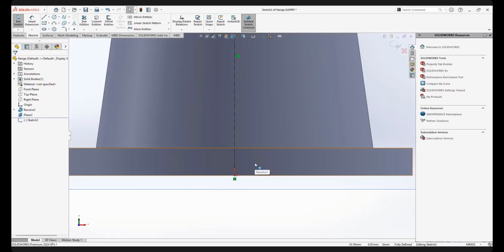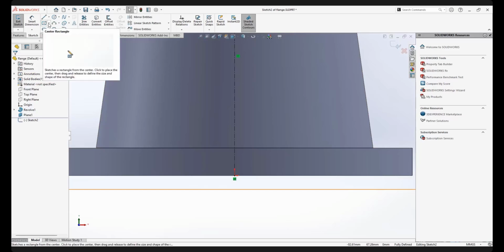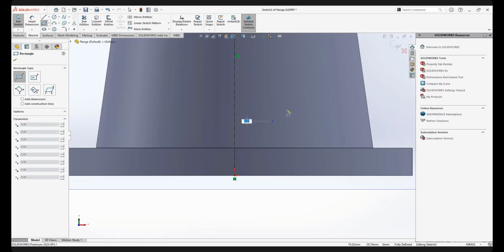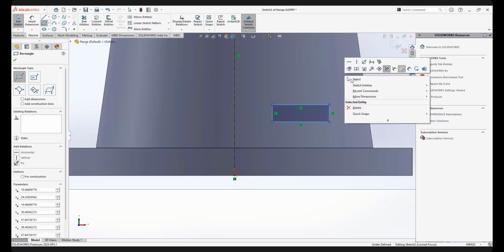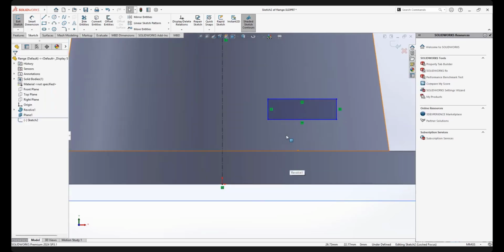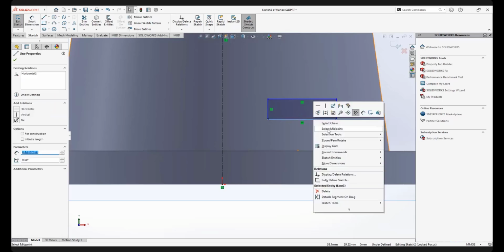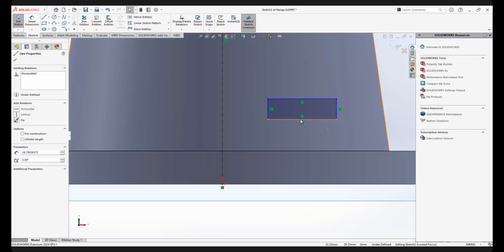Okay guys, this is another thing. I will teach you one way: I can simply draw a corner rectangle. I can put it here for a while, okay? Are you watching, class? Okay, watch me carefully. Relation. I select this line. I bring my mouse here. It highlights the bottom edge of the rectangle. Right-click the mouse, select midpoint. So it identifies the midpoint of that edge. Can you see it? The dot?